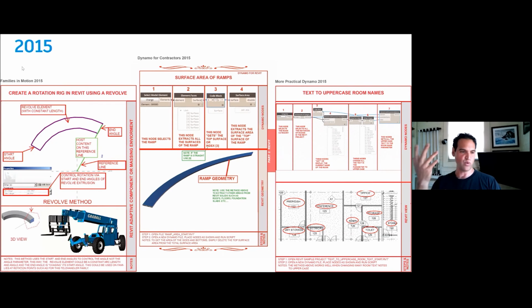Like if you wanted to build a window or a revolving door, but you can use a revolve actually. A revolve doesn't have to revolve 360. So you can build a revolve, some solid object, and open it up, much like you see down here. Then you get this flat face you can host things to. So you can host geometry to it, and then you can open and close that revolve as much as you want, and that will simulate rotation. And it's actually very stable. So when I build anything that has rotation in the classic family environment, I will use this revolve method.